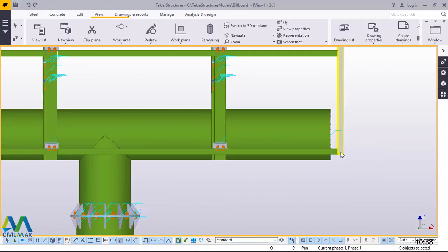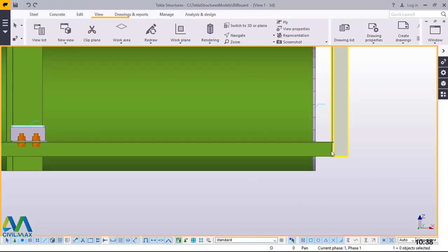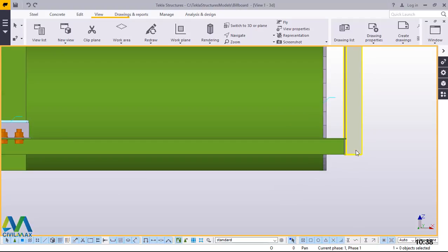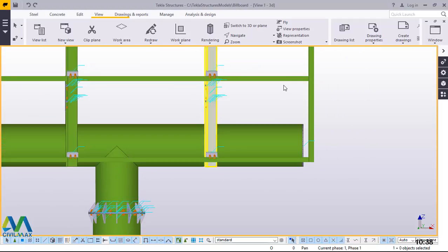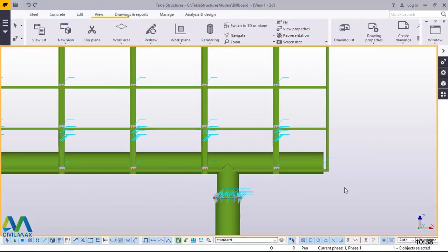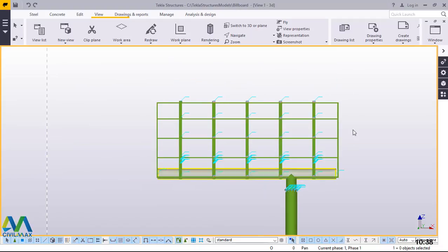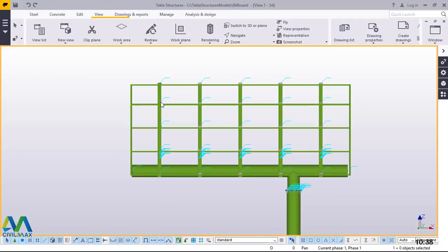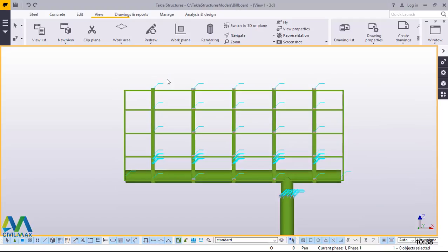Now this is how it looks. If I bring it close, as I told you, this one you can weld once this has been erected up, or this frame can be welded together, so when you fix it up you can carry the whole framework, then bolt it straight to this beam by help of a very light crane. It's not a matter that you should use a 20-ton crane or 18-ton.